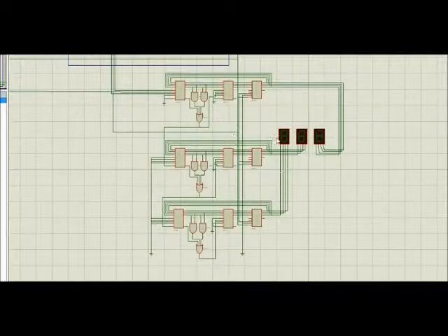What it does is, it stores the binary coded decimal representation of the current score of a player, and when the game switch is pressed and a new number comes in from the random number generator, it adds that number to the current score of the player to give a new score. Then the score is displayed in 7-segment displays.